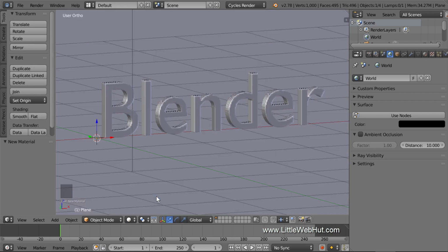Next, we're going to set up dynamic paint. To use dynamic paint, objects are set up as brushes and canvases. In our case, a sphere that we'll be adding soon will be the brush, and the text will be the canvas. After the dynamic paint is set up, we'll be able to use some nodes to make the text become visible as it's painted with the sphere.